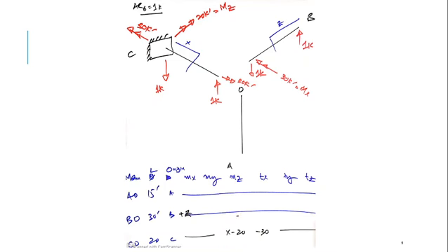In order to construct F66, Z would be multiplying with itself, Z squared, and you should apply dz here. As it is a simple moment, it would be EI here, and it would be 30. Using a calculator you can easily evaluate it. You have been solving these integrals since your FSc, so it's very easy.